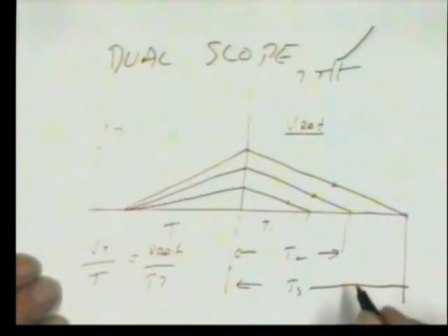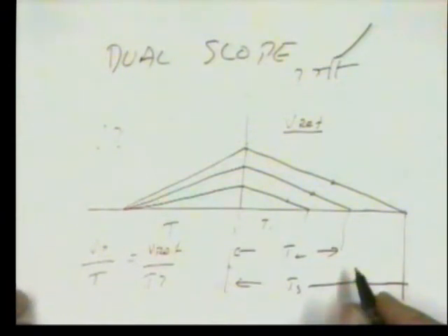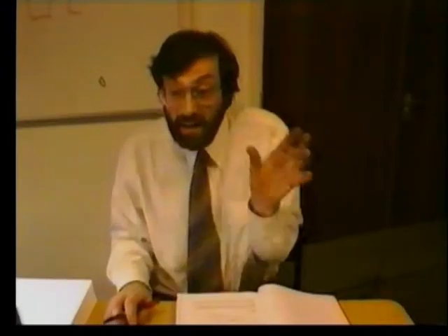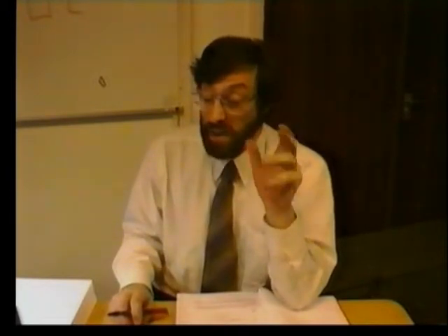It's a direct linear relationship. So using an extremely simple, low-cost electronic component, a capacitor, which costs less than a penny, and a little bit of logic in your computer, you can implement your own dual slope ADC extremely easily under program control.